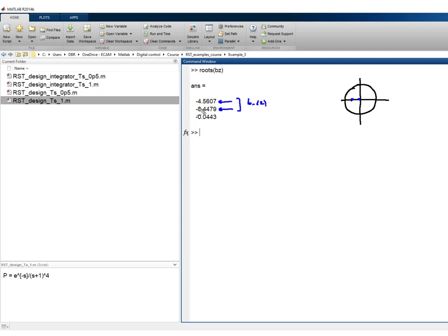If we don't, this will produce an unstable pole zero cancellation, so this would be catastrophic. But this one, we would have it in the denominator, and this would produce this oscillating behavior, and since it's too far from the origin, it would last too long. So this one goes into B minus. This one is still negative, but it's so close to the origin that you can put it in B plus, right? So let's see and have a look at what we have done.